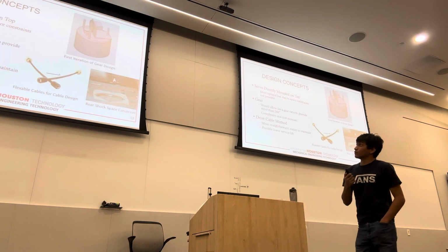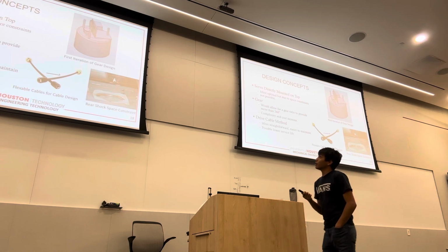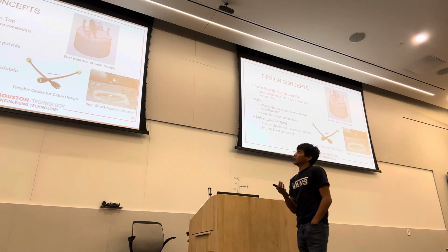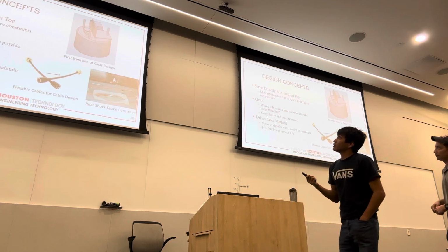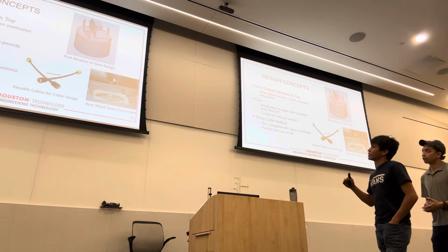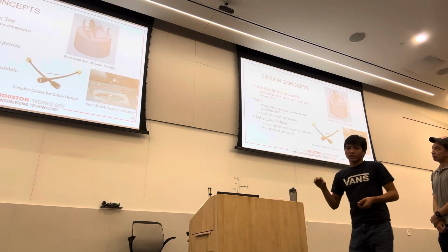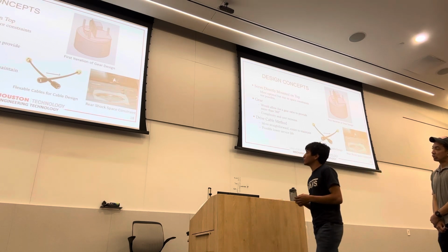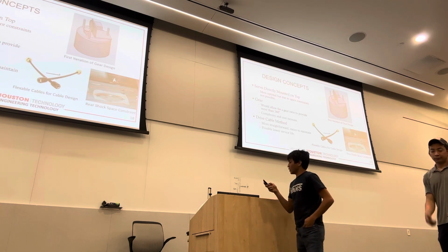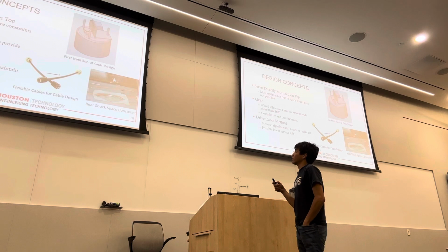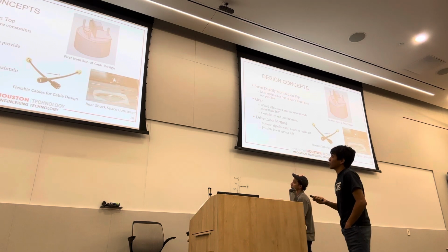So design concepts. There are a couple options. Ideally, you put it directly on top of the adjuster, but we just don't have enough space. You have the gear design, so you can move it off to the side, lower the stack height, and then you have the drive cable. So it's just a flexible cable that can transmit torsional motion. They have it usually for manually adjusting coilovers if they're behind panels. I've also seen it in flexible screwdrivers and stuff, so that was our other method.